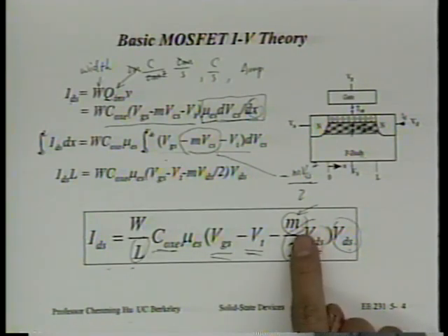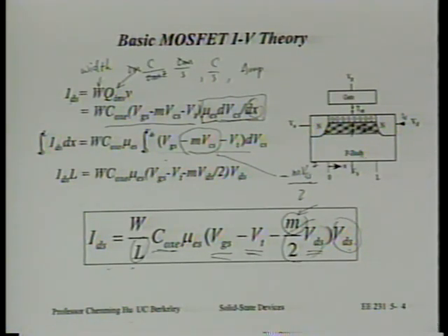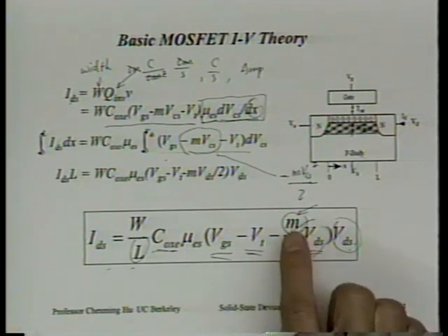Especially with this addition of the body effect or the bulk charge effect. I don't like the term body charge effect. I think the backgate effect is actually a better name. I'll explain in a minute. This becomes an even more useful model than without that M, right?